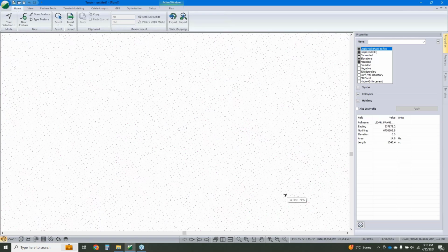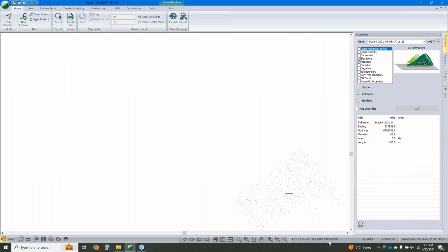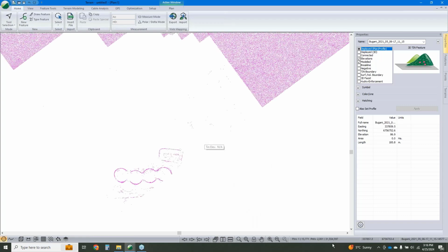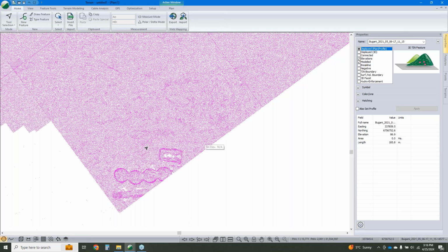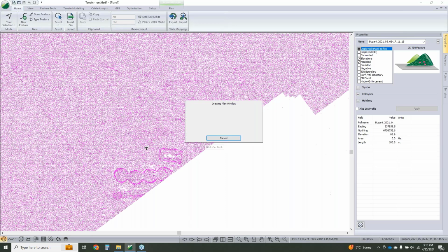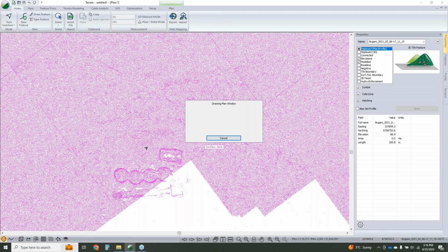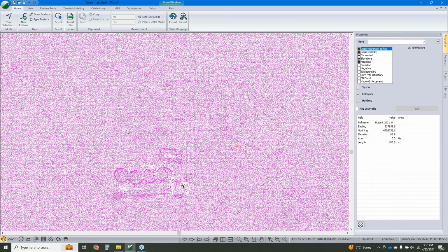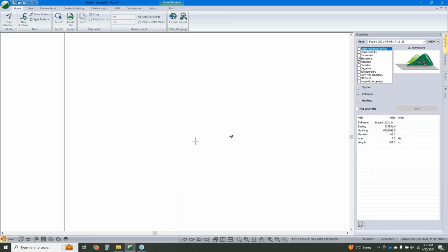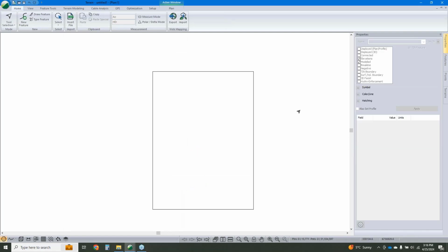And as Aaron introduced, well, if 10 million modeled points is a good rule of thumb, this one's going to be probably pretty sluggish if we model it. So we're going to thin it. And in this case, we don't need to identify whether we want to keep the full resolution in this area or not. The whole thing is so dense that we can reduce the resolution for all of it after that's been imported. I've clicked off to the side to deselect those points.